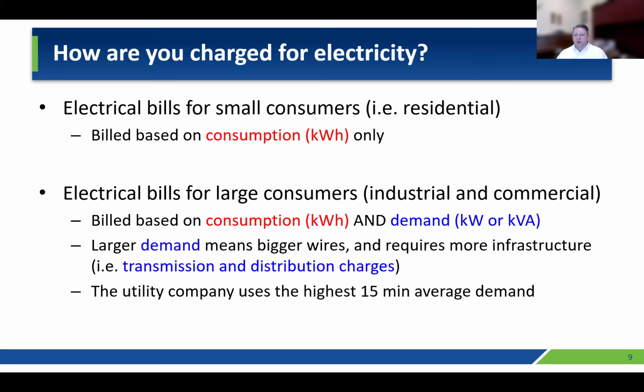And for many consumers, industrial and commercial, their bills are approximately half and half, or maybe 60-40, between consumption and demand. And so it's not just about how much total energy you use, it also matters when you use it.